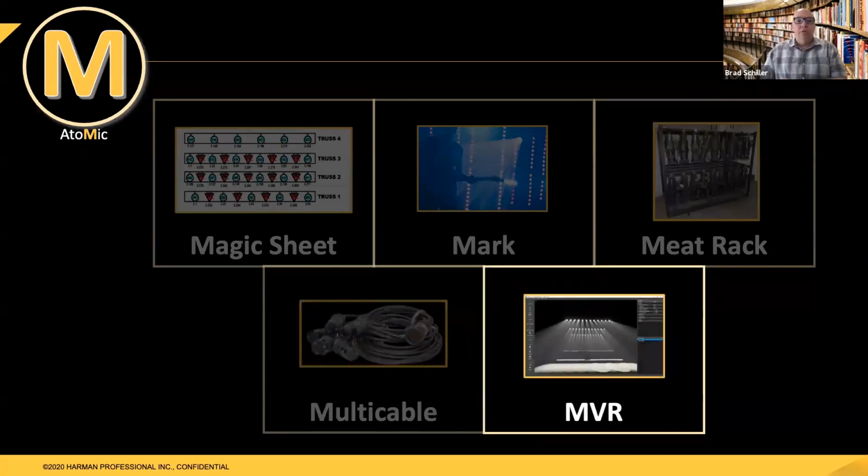Now here's another new term called MVR. What MVR stands for is My Virtual Rig. And this is fairly new, another one of these new terms. And this works hand in hand with GDTF files. And what MVR does is it gives you this, again, I'm going to call it a container. It packages the GDTF files of all of your lighting fixtures as they are associated in your design. So it has the 3D model, and it helps describe not just the fixtures, but where they're placed in a 3D model. So it tells you where they're positioned and maybe other elements in that 3D world, such as set pieces and things.